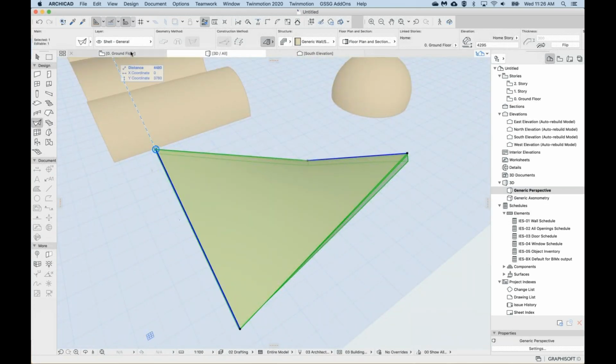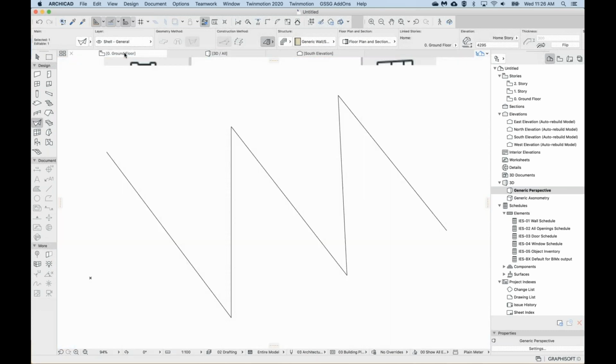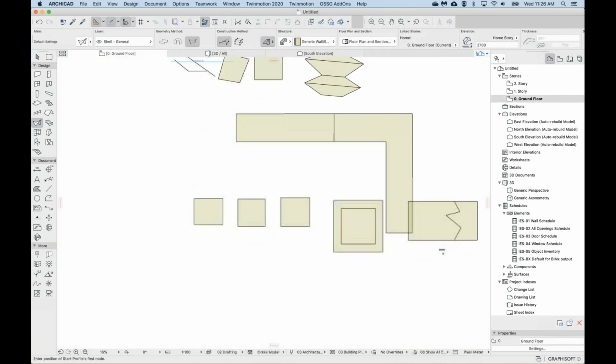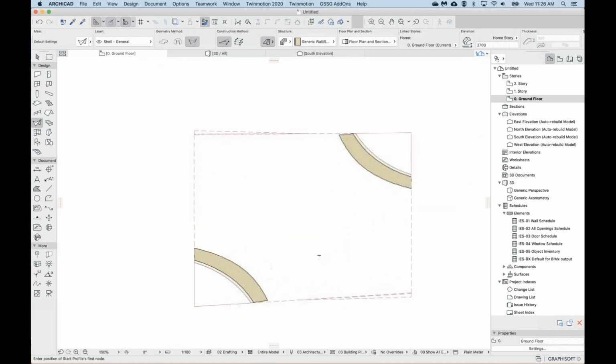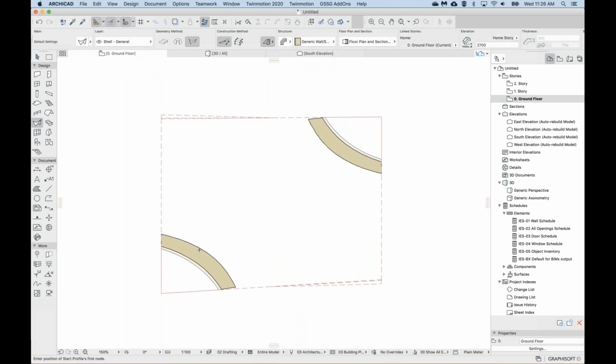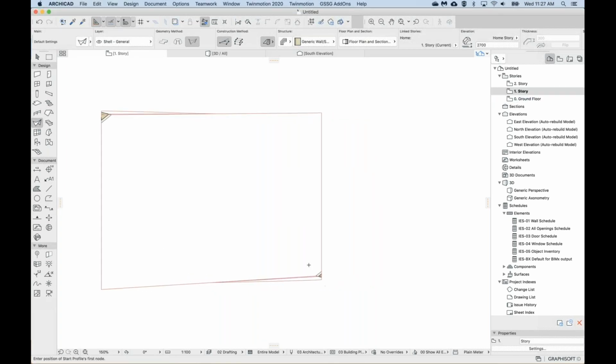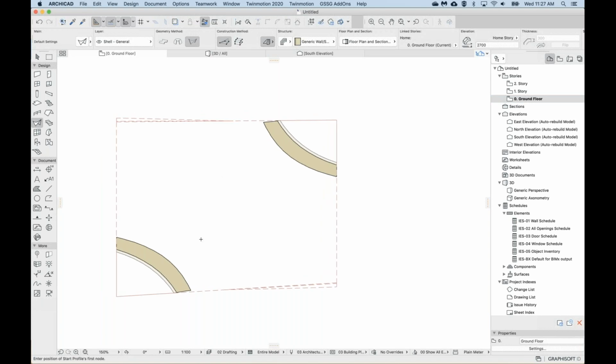Okay, so if I go to the floor plan, I'm going to switch now to the floor plan view, and I'm just going to move around until I can find that shape. So here I can see it here in my floor plan. So you can see that the floor plan shows how it's cut at the floor plan cut plane, at like the 1.1 meters. So if I move up a level, for example, then I can see, okay, this is not so tall, but each story will show me exactly how it's cut and projected onto the floor plan.